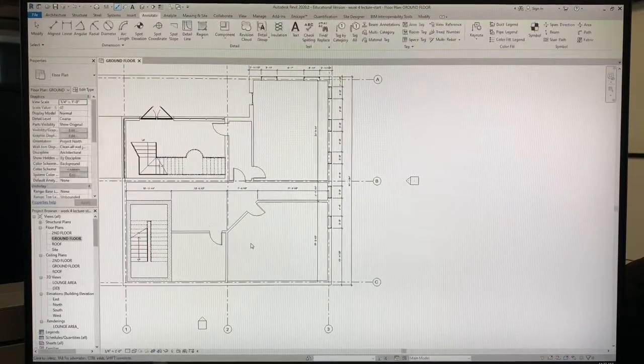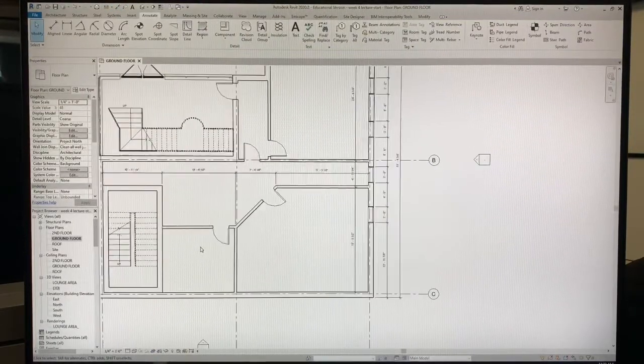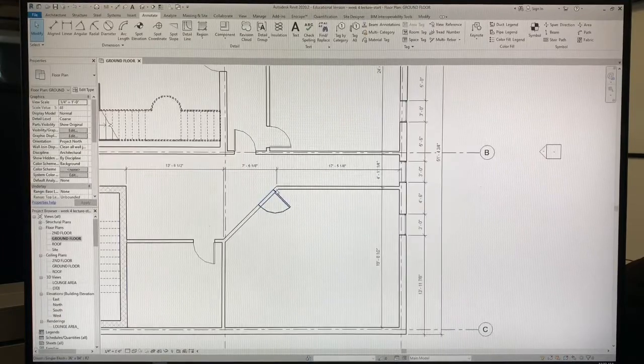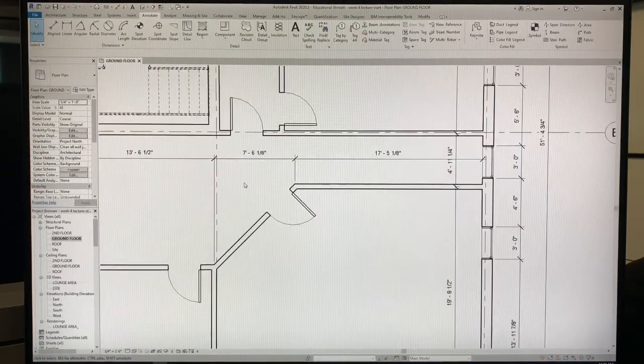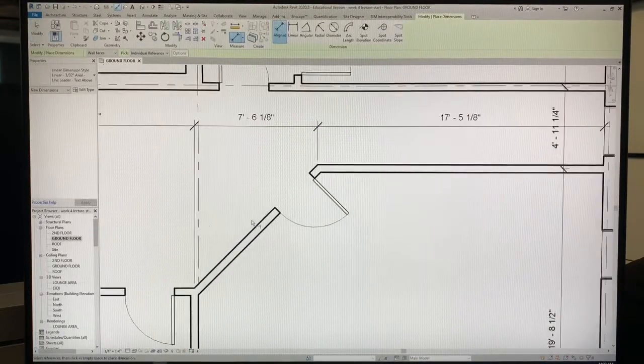All right, now, how do you dimension an angular wall? Normally when we dimension a wall like this, a diagonal wall, we dimension the X and Y. We don't normally dimension the angle, but I do want to show you how to do that. So let's go to the Align tool, and again, we need to pick these 2 points.